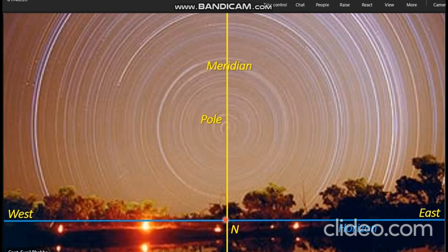So I point the spin axis of my free gyro to this endpoint. Now, if my gyro spin axis is pointing towards this particular point, the endpoint in the diagram, point N, that means my gyro star is also going to be here. So you can see the gyro star in the diagram now. We have shown the gyro star at particular point N.